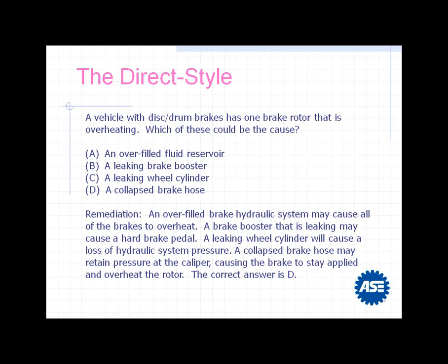Okay, a brake booster leaking, that might cause a hard brake pedal, but again, more of a common denominator type problem. Leaking wheel cylinder, loss of pressure, okay, not increasing the applied pressure, okay, but the collapsed brake hose may retain the fluid pressure at the caliper, won't allow the caliper to retract back, and so therefore it stays applied and gives you an overheated rotor. So in this case, our collapsed brake hose is the correct answer. The correct answer is D. Okay, so